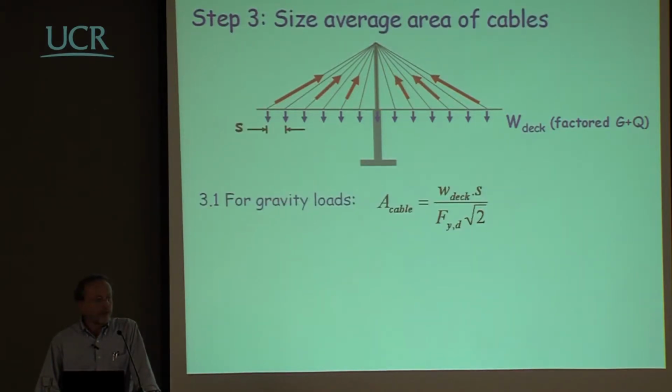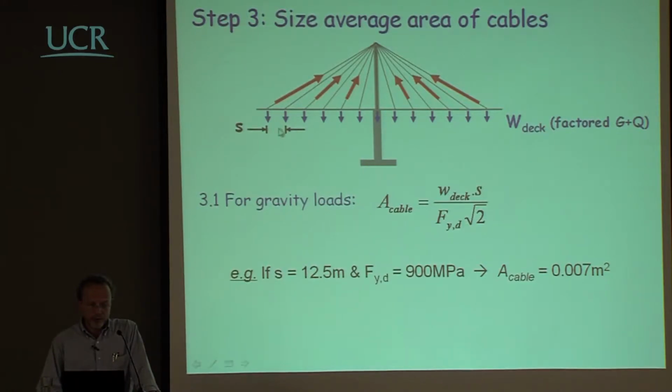And then maybe you try to dimension the size of the cables, and again, this is not too difficult, because you will set up a distance between the cables, so you know what is the weight of the deck, and you end up with some sort of average figure. I'm saying average because you have different forces here and here, but for the time being, you only want to know what is the amount of material that you need to put there.